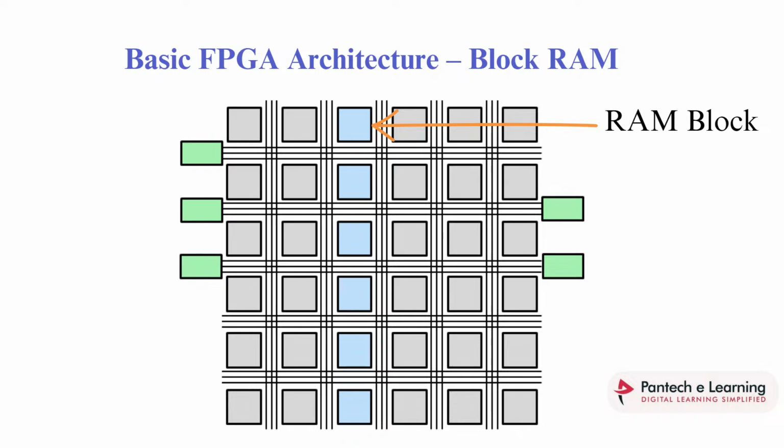And then we go into the RAM block. We can assign the RAM block on FPGA also, but the FPGA has a separate internal configuration memory. Internal configuration memory is nothing but the memory where we have to load the code in the FPGA. But we can also change the FPGA to RAM by assigning some large CLBs for the purpose of RAMs.